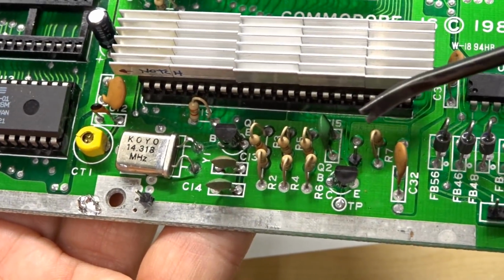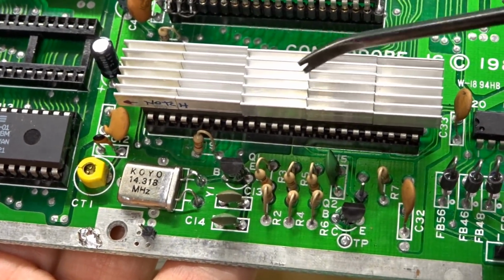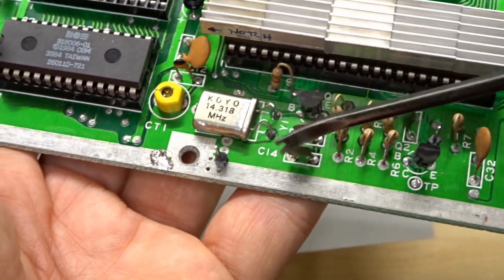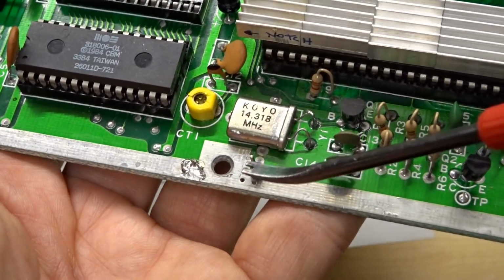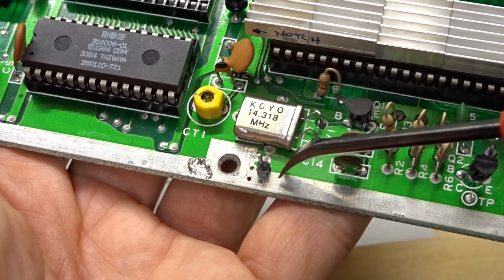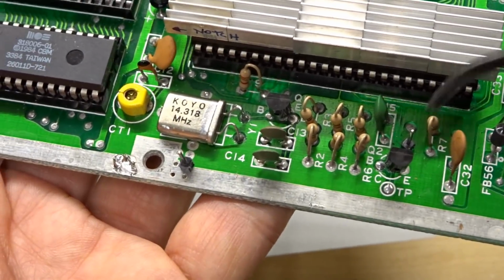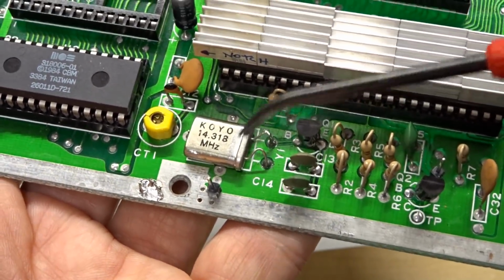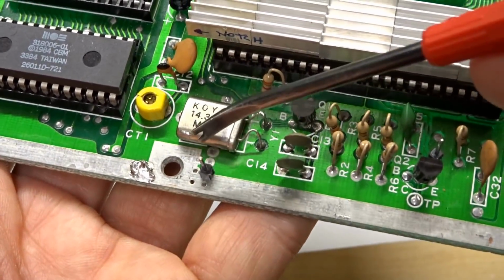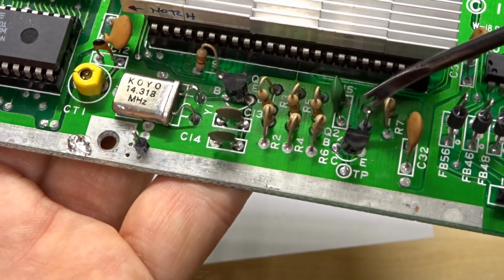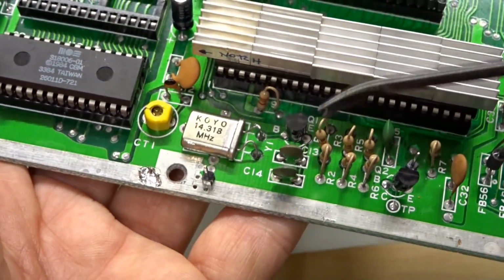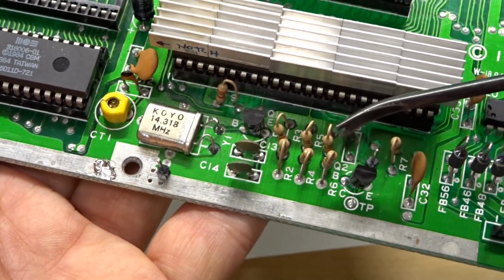One other thing to consider is you want to make sure you have a really good ground for the clock signal going into this. It's relatively high frequency, so I decided to put a ground pin right there in the main ground plane. That was sort of the closest one I could find. And I actually power the little clock synthesizer board off of the EEPROM socket, but I take its ground right from here, and then I feed the clock signal into there. And on the oscilloscope, when I look at pin 14, it's a nice, clean TTL clock signal.